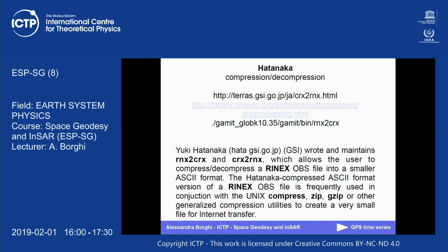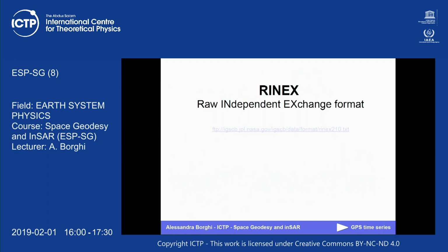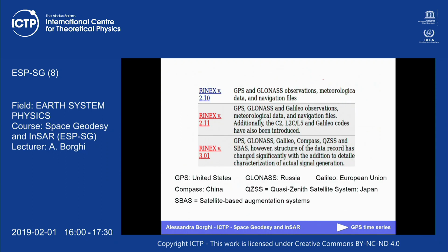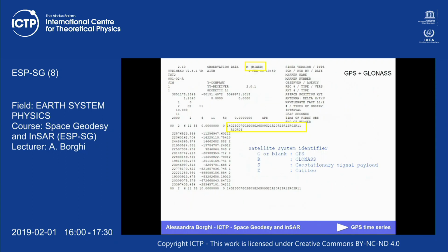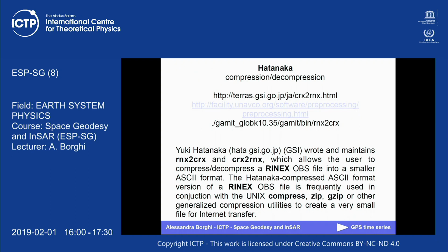So often you have a file with extension D. The RINEX file ends with O, meaning observation file, and D when the observation file is Hatanaka compressed.